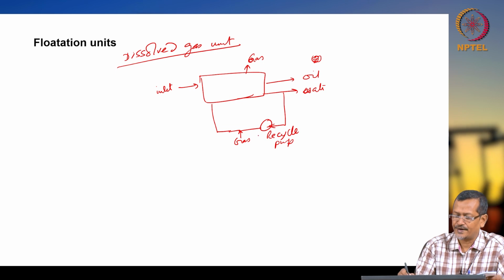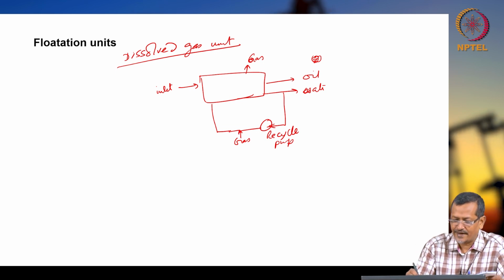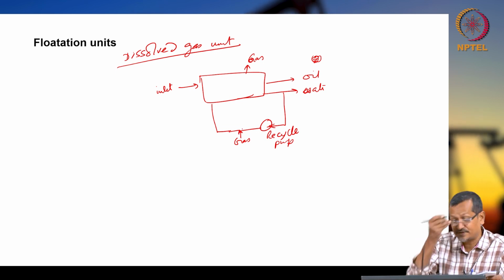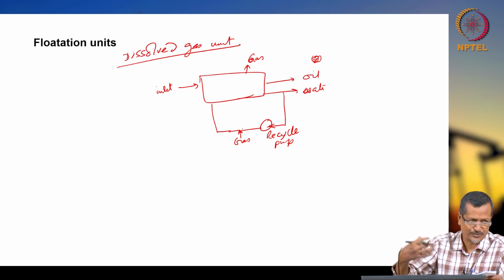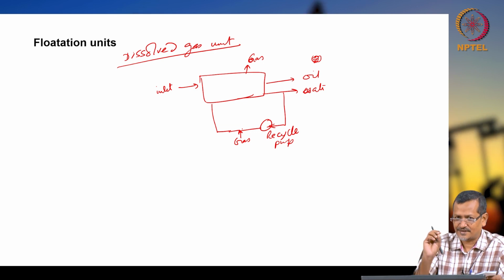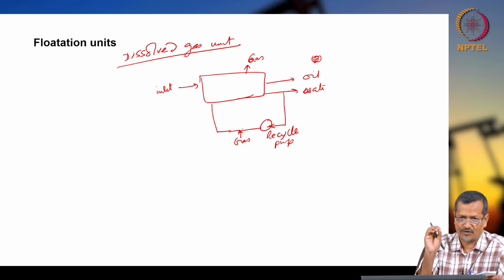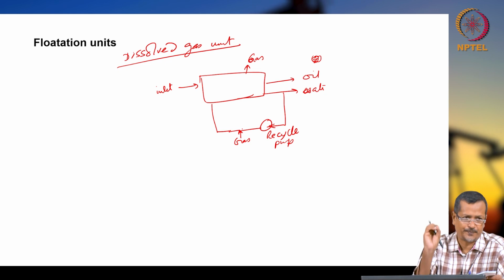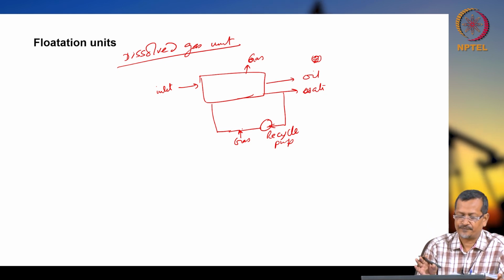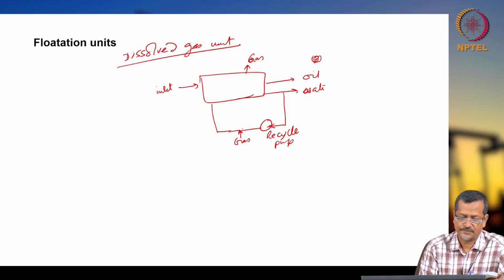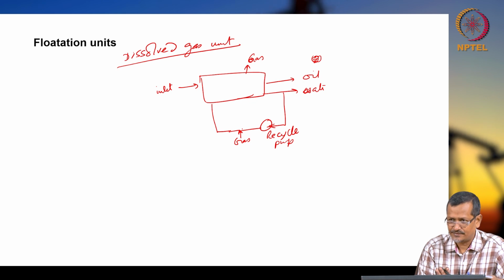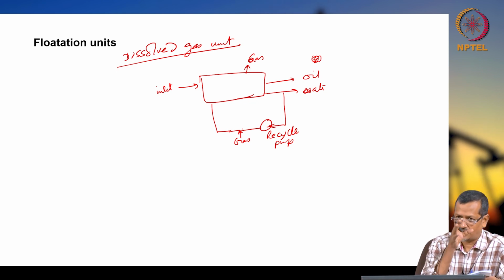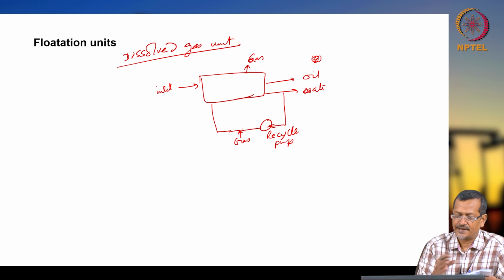Whatever water you get, you recycle, but you add gas. The gas mixes with the water and creates flotation, making it easier for oil particles to move up. It can be used in different ways, but in many cases upstream also.